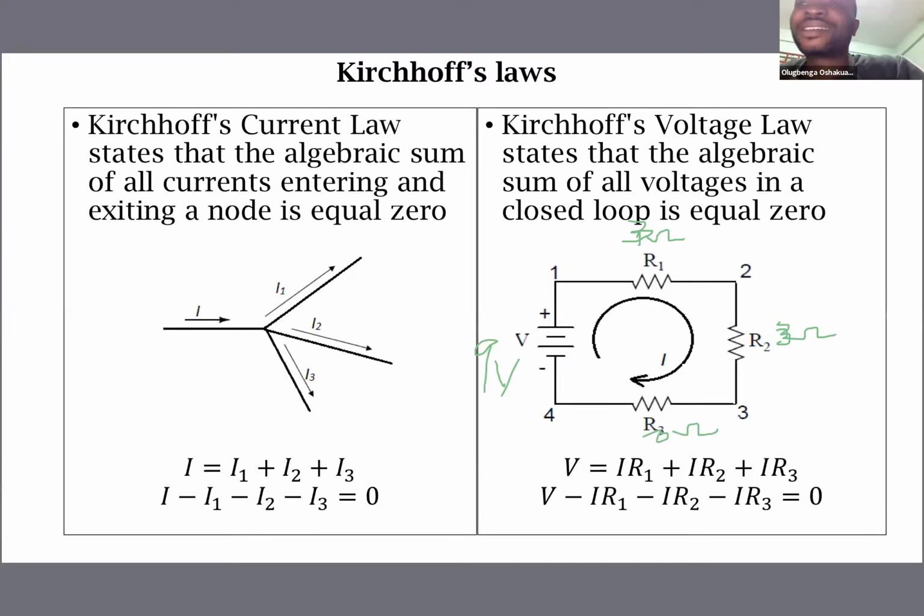When you connect this to the battery, you would expect that a current of 1 ampere will flow out of the battery. When a current I equal to 1 ampere flows out of the battery, 1 ampere will flow through R1, and a voltage of 3 volts will be across R1. The same current will flow through R2, and a voltage of 3 volts will be across R2.